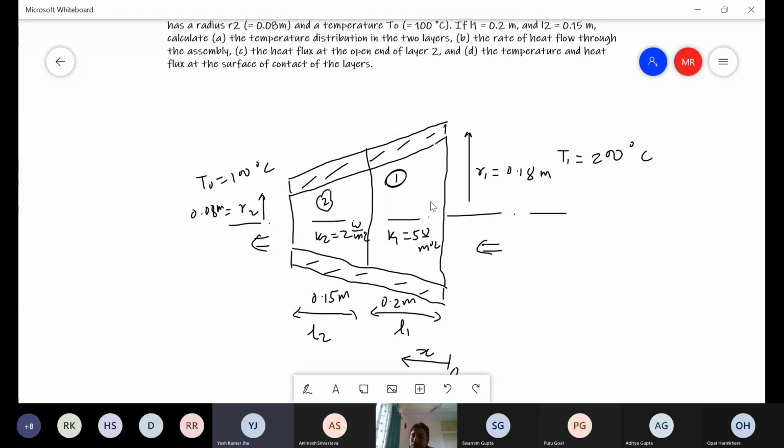As we are going, why is it not varying if we increase the R? Capital Q you are saying, or small q? Small q. Small q is varying as we are moving along the x direction, but across the radial direction, if you are saying in the radial direction, remember there is no heat transfer taking place outside here, isn't it? I understood your question. You are saying that there will be a temperature distribution along the radial direction as well. That is what you are trying to say?